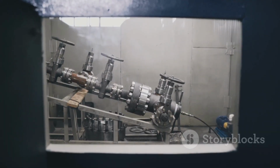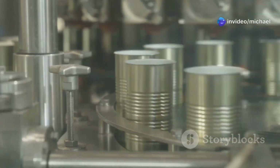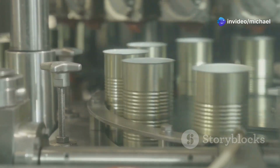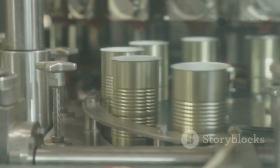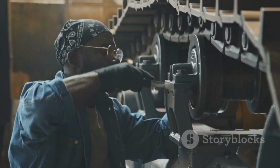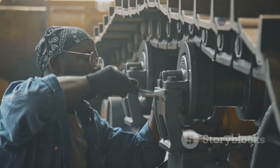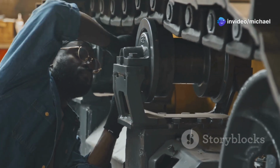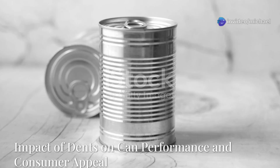Another cause is malfunctioning equipment. If the machinery responsible for forming, filling, or sealing the cans is not calibrated correctly, it can exert uneven pressure on the can bodies, resulting in dents. Furthermore, worn-out parts or a lack of regular maintenance can contribute to equipment malfunction and increase the likelihood of dents.